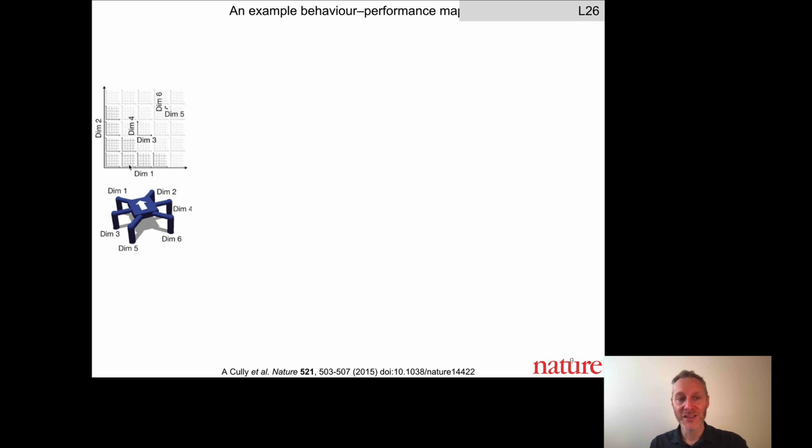You'll notice that this bin itself is broken into a smaller set of 5 by 5 bins, which correspond to the third and fourth leg. For the same single controller, we look at the fraction of time that the middle left and the middle right leg spent on the ground, and that will allow us to determine which of the 25 bins in here we should place that controller.